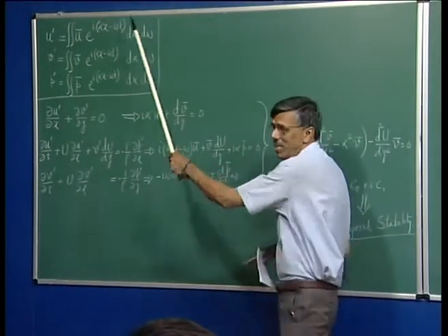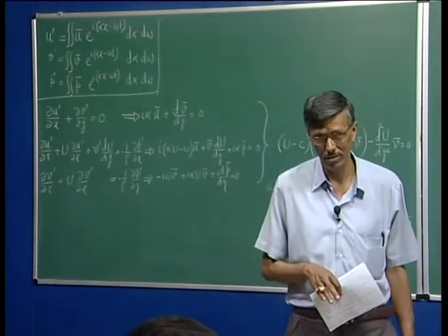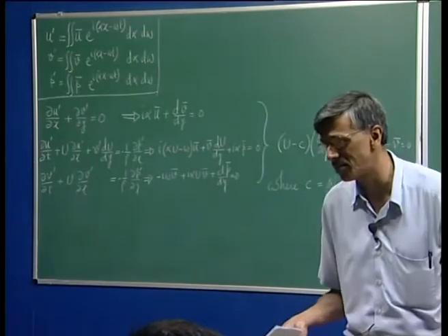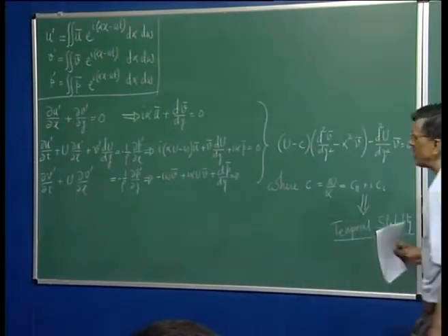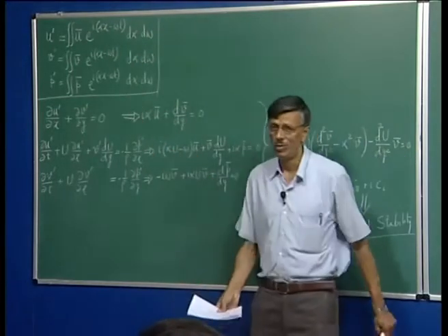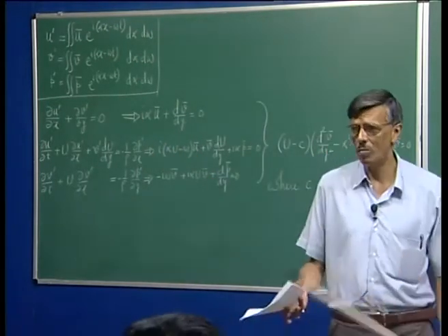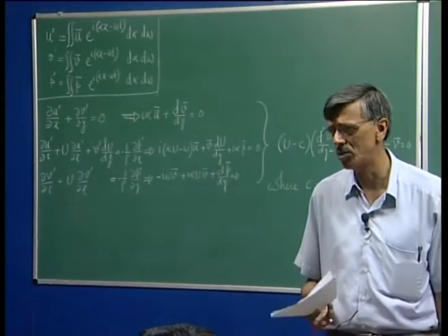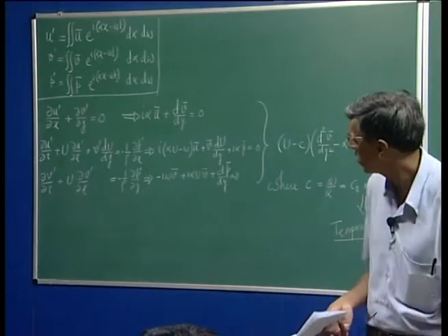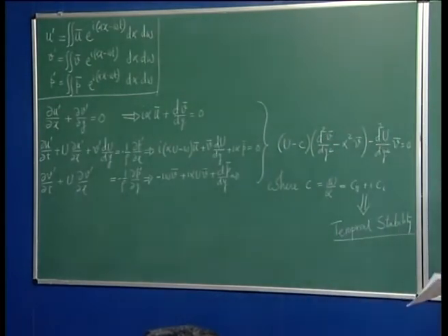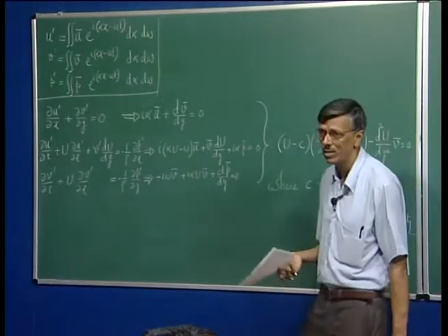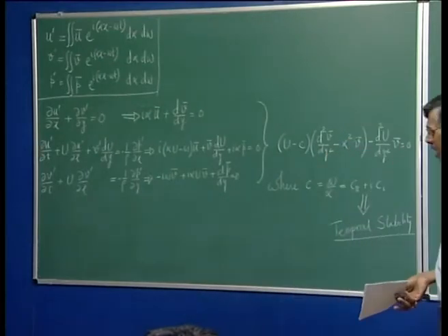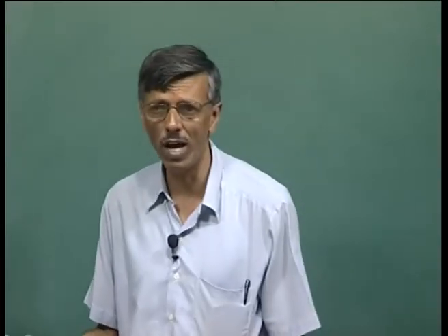What about the time variation? Omega also can be a complex quantity. The real part will of course once again define the phase. The imaginary part, now because of this additional minus sign here, if omega imaginary is positive, it is going to be unstable for a downstream propagating disturbance. Whereas if it is negative, then for a downstream propagating disturbance that would correspond to stability. Okay.